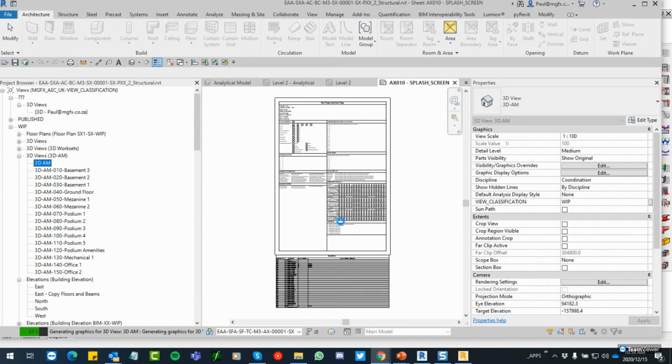Some of the tricks that I'm learning as I go along is that you can work in groups. When you do floors in groups, if your beams are the same all the time, then they do connect the nodes as well, which is great. Where it becomes complex is with things like parking ramps. That's one of my regions of interest: to use Robot to model the parking ramps for this building, simply because Revit doesn't do that very well.